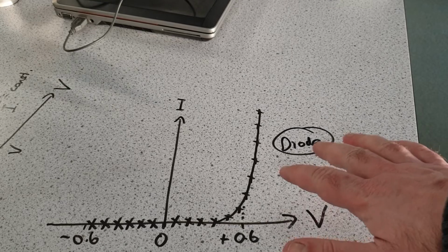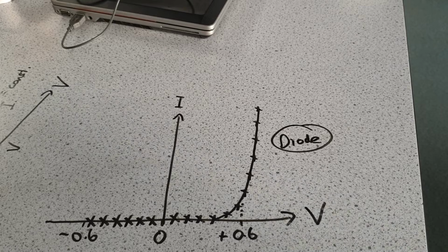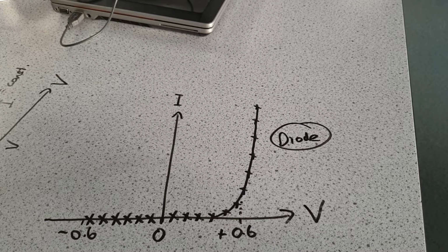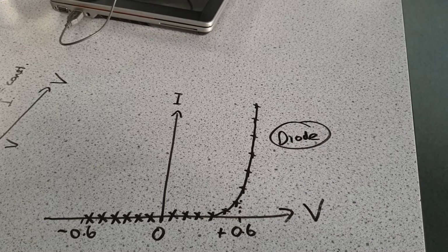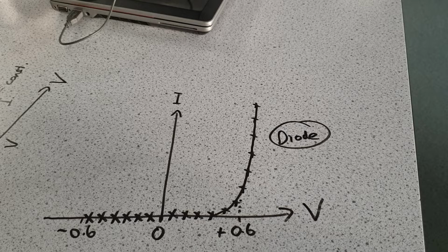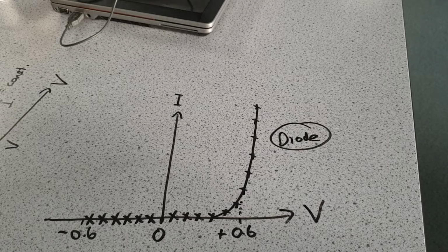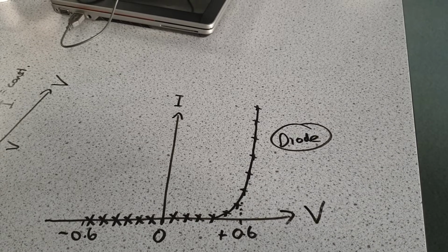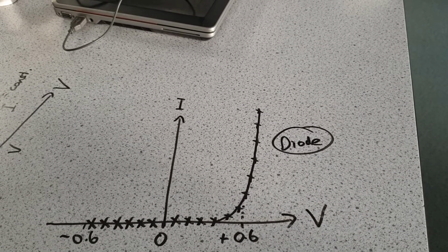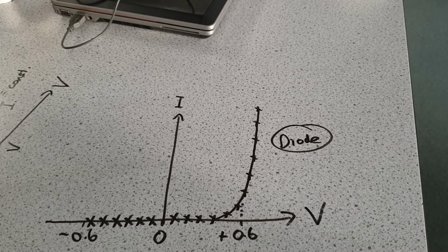As far as what diodes are used for, they have a number of different purposes. One use is to protect other components that are sensitive to current going through them in the wrong direction. For instance, if somebody by mistake put the battery in a device with the negative and positive terminals the wrong way around, you wouldn't want to damage the device. So a diode could be in the circuit within the device to protect other components from current passing the wrong way through another component.